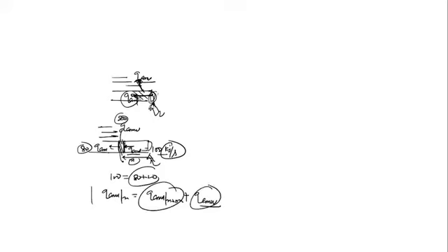Is this again 100? No, because here energy also gets transferred through its perimeter via convection, because here the fluid is in motion. Yes or no? Its Q convection is there through its perimeter. So if it is 80 here, then this would be 20 here. So this 100 equals 80 plus 20, meaning Q conduction at x is equal to Q conduction at x plus delta x plus Q convection. Is this clear, beta? So simultaneous conduction and convection is taking place in this example.